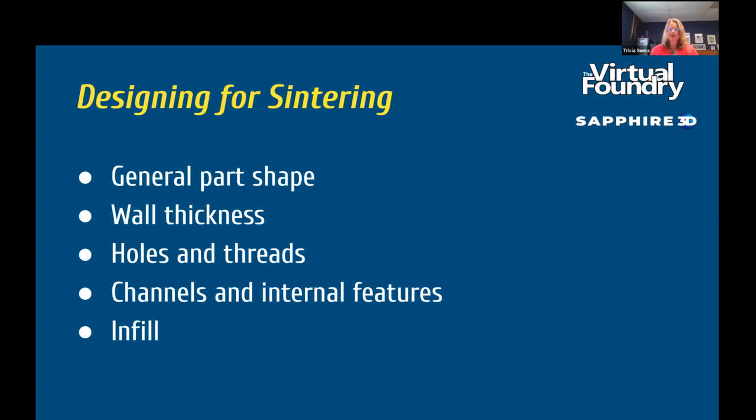We talked earlier about that support material and how you were removing those supports before going into the debind sinter process. And we should mention that the part shape is supported by a refractory ballast. We have different materials for the different metals that we offer, and we can tell you more about that offline. We are using a sort of sintering powder to support the part shape during the sintering process.